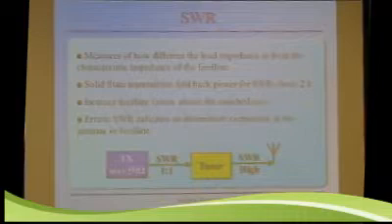But now, these solid state transmitters will mess up the final power transistor if the SWR is above about 2-to-1. So they put in circuitry that starts cutting back the power once it gets above 2-to-1. So if your SWR is above 2-to-1, your 100-watt transmitter is now only putting out 70 watts. Or if it gets above 3-to-1, it may only be putting out 10 watts. So it drops off pretty quickly, so you have a real strong incentive to keep the SWR below 2 to 1.